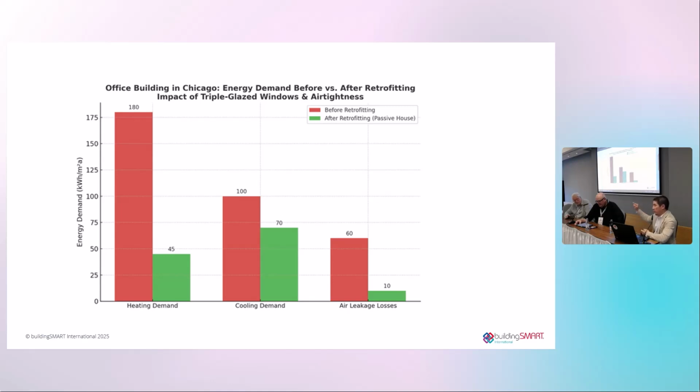Plus, we integrated louvers, or jalousie, or shading devices that affect not only heating demand but, in that case, cooling demand. So we protect ourselves from the lower altitude sun during winter, or let's say fall and spring times as well. So that was the point where we reached our energy efficiency by simply doing the first retrofit step, changing windows and improving air tightness.